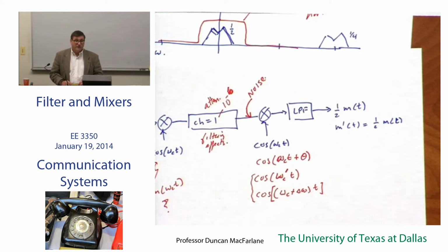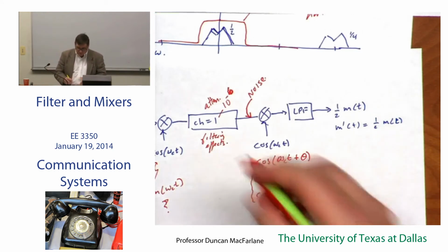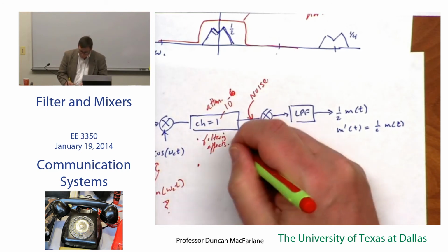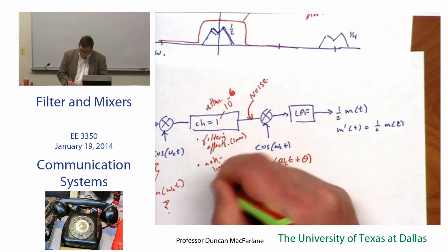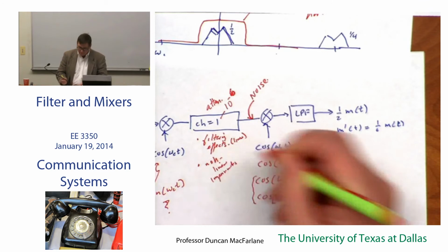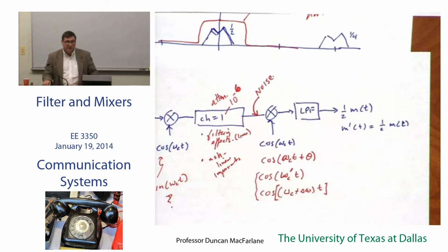And then you might have 160 channels in that fiber at once. So there's a tremendous amount of light power in that 9 microns, and you might stay in that fiber for 9 megameters, which is a heck of a lot of molecules to tickle. And a heck of a lot of molecules to tickle, not in a linear sense, but in a nonlinear sense. And so if this is linear, there's also some nonlinear impairments. Okay? So in many systems, there's nonlinear impairments.